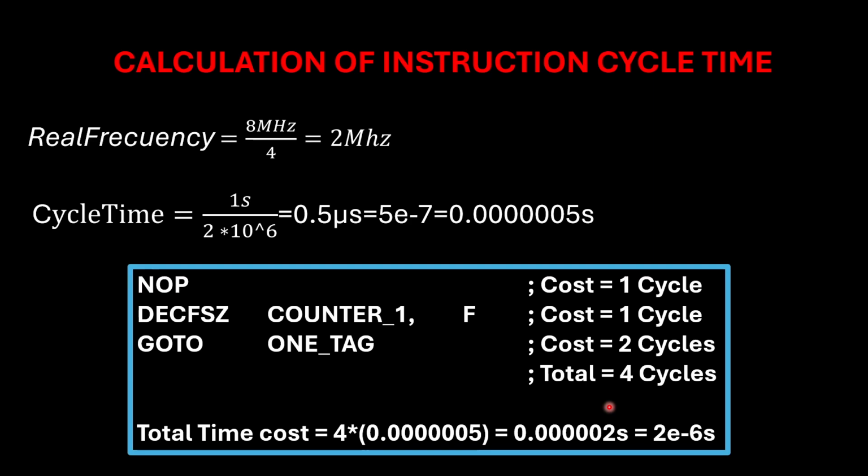Actually, I don't think that would even be possible, because perhaps the memory of the microcontroller would run out. So in order to mitigate all of this work involved in creating a 1 second delay, we can create nested loops, okay?